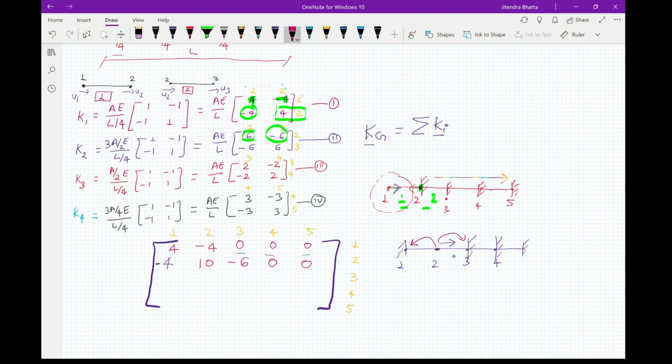Therefore, it will induce a force at F3 and induce a force at F1 as well. Therefore, we have 3 values here, and these all must be in equilibrium. Therefore, generally, when you are only looking into forces, the sum of each row should be equal to 0. When you have a common variable outside, you can see that these will be additive.